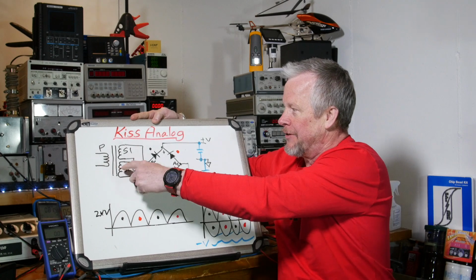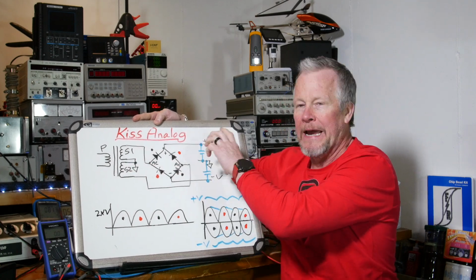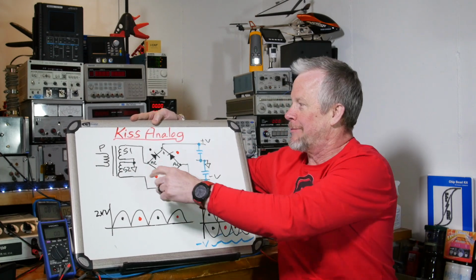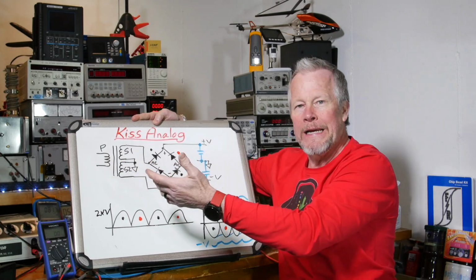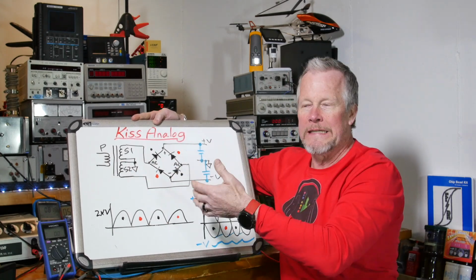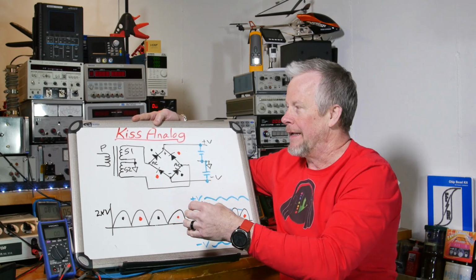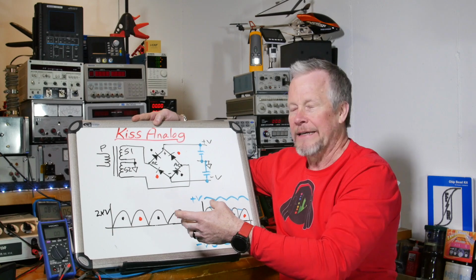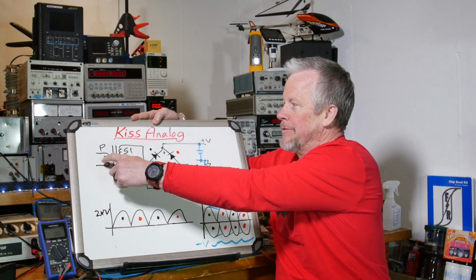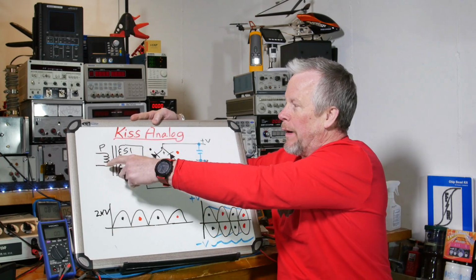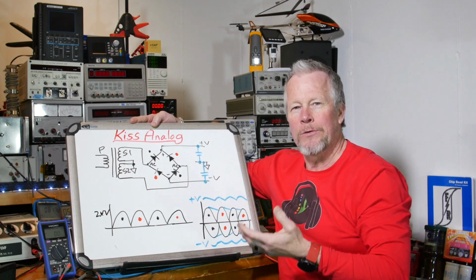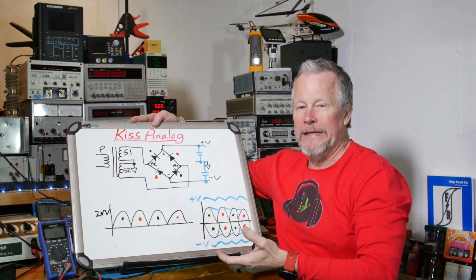The power supply: transformer, rectifier, and the volt capacitors. I'm showing the transformer as a single primary. Really on this transformer, either one of these, there's two primaries. You stack them if you're doing 220. If you're at 120 in the States, then you put them in parallel, so it looks like just one transformer winding. And then on the secondary you have two, and you stack those in either case.